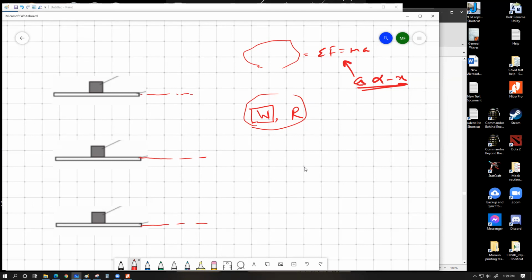If we consider the two terminal positions, you would have the maximum requirement for this force. So let me just draw this force in red. Let's say the maximum value of this force you're going to need over here is this much. The maximum amount of resultant force you're going to need to maintain simple harmonic motion over here is this much. These are two values of maximum force, which can be mass into acceleration, which is m omega square a. Now this resultant force should be coming from W and R. If I try to draw the W force in different places, it is possible.